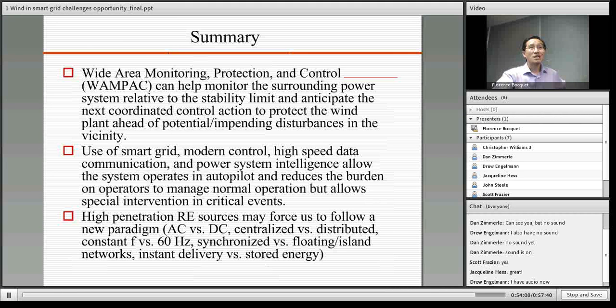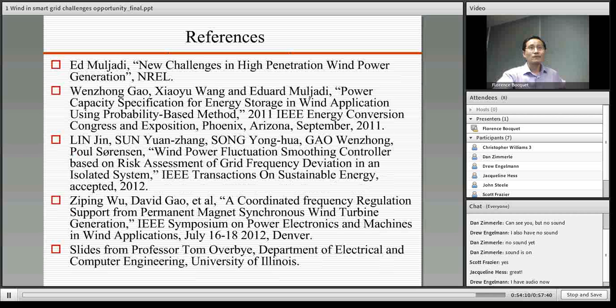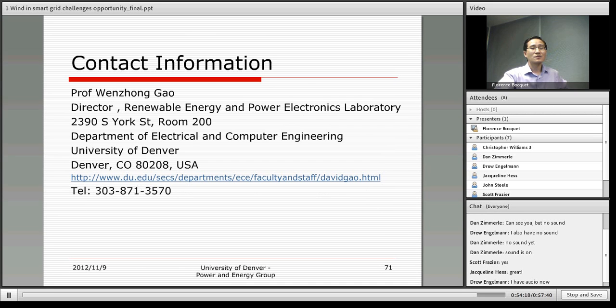I was wondering, it looks like you're designing batteries and capacitors to go on individual turbines. Yes. And I thought once we connected all the turbines in the wind farm, the power would already be a bit smoother. So I'm wondering if you considered putting that storage after the connection. Yeah, you're right. We can put energy storage on the wind turbine generator, but also at the wind farm level, combining. For example, at wind farm level, you can use flywheel energy storage or flow battery, and so we can do a trade-off. So why is it ever better to do storage at the single turbine scale? Why not do it at the front?